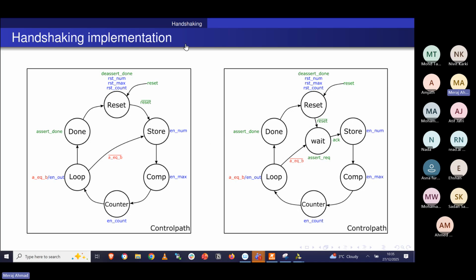So these are various ways; it depends on whether it is an ADC or a separate digital block. It can be a memory, it can be a FIFO. How this data is coming in depends on your application. This is something you get as a problem in your specification document: okay, this is something coming from a memory or an ADC. You then need to think about these interfaces, and based on that, you can implement the controller. Implementation-wise, if you can make this on paper, then it's a simple translation.